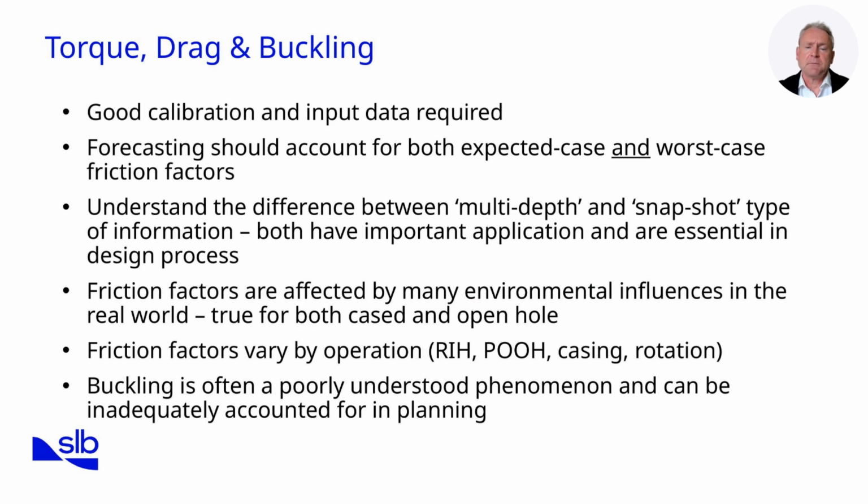Torque, drag, and buckling are mechanical limits that often control ERD design. Accurate forecasting requires good calibration and reliable input data. It's important to model both expected case and worst-case friction factors, since real-world conditions rarely match the ideal.